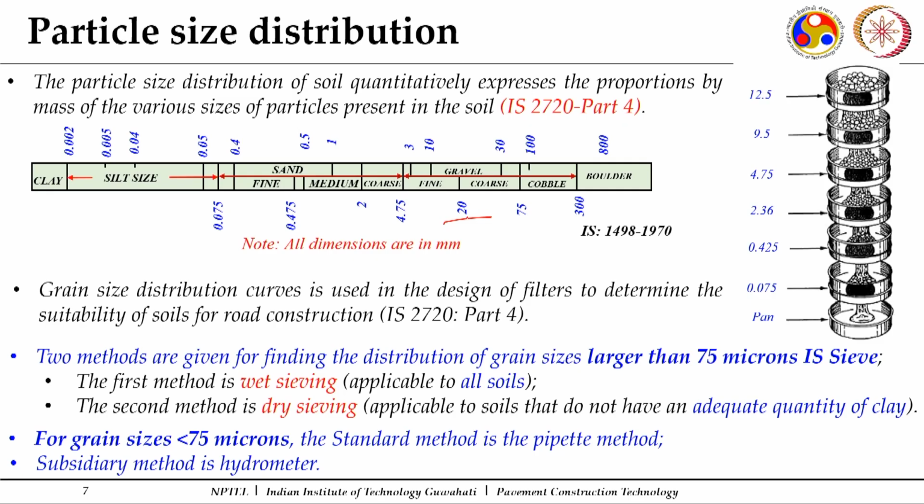Now, as I mentioned, what is gradation or soil size distribution? I can pick up the sieves where the material is expected to lie. If a material has sizes ranging from, say, 20 mm and going below, even lesser than 1 micron, I try to do sieve analysis accordingly.